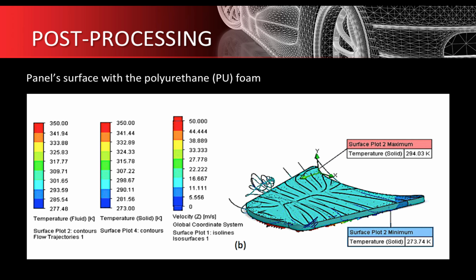material. This has significantly influenced the temperature distribution of the interface between the outer face of the hood panel and the PU film. Therefore, the heat quantity on the surface above the panel at point T2 is transferred slowly across the PU film to the outer surface of the PU film. Moreover, heat transferred by means of forced convection is also considered in both of these simulation analyses.